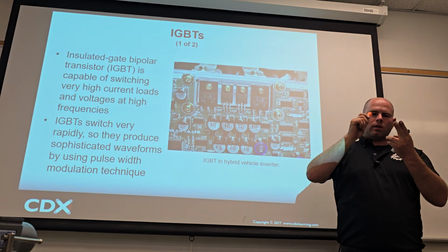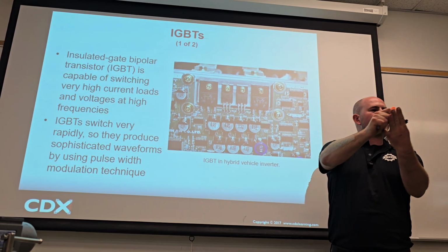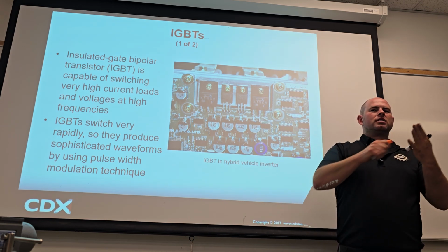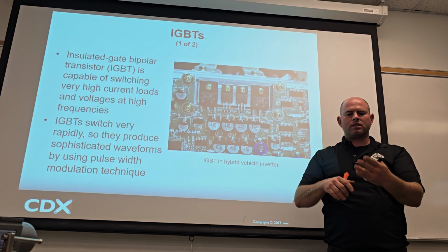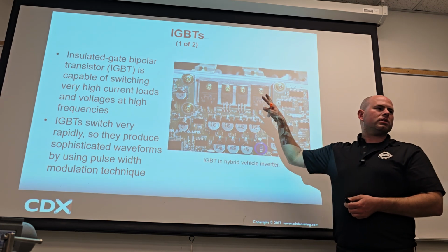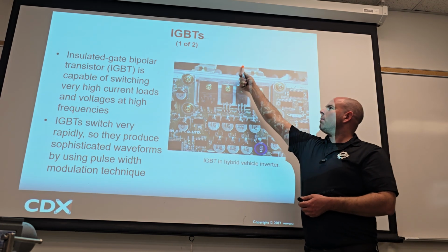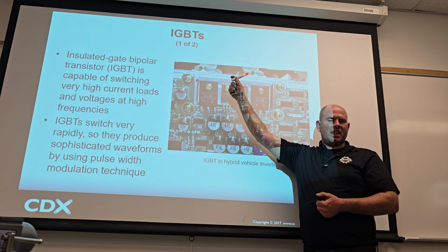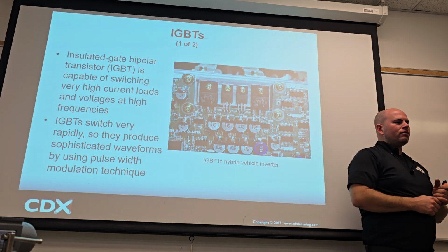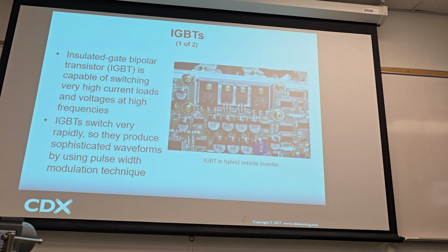Yes. How? I did it like this. What was the result? It was like this. Did you test the wires? Yes. How? Tested resistance, tested voltage drop, these types of things. If those two are good, the only remaining part is here. And we could do some tests on here, like check the output outside, and that's all anybody's ever going to ask of you. If you could do that, you're going to do just fine.